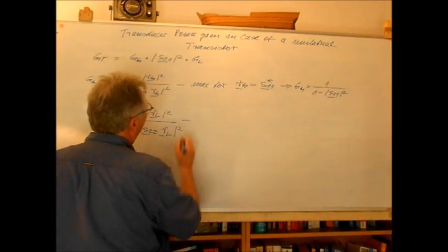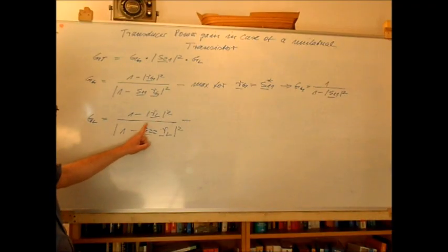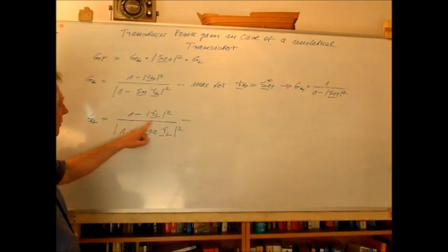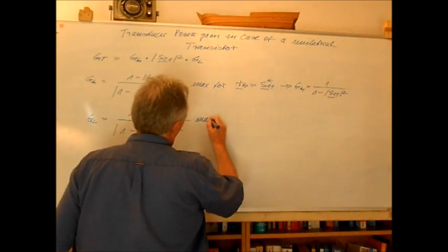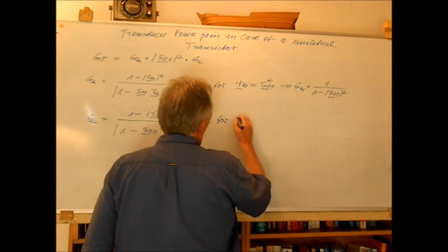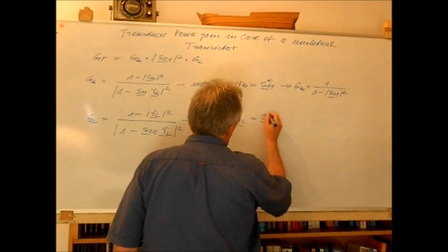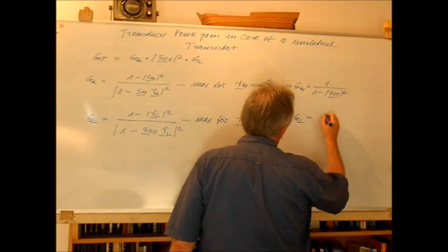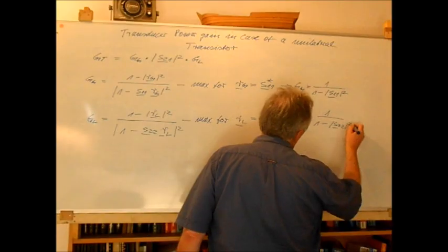And also here, for this, we can find the maximum of the load gain again. If I assume a transistor at a certain point of operation, S22 is fixed. The only thing we can change is the load reflection coefficient. And also here we find the maximum: RL must be chosen equal to S22 conjugate complex, and for the load gain we then get 1 over 1 minus S22 absolute value squared.